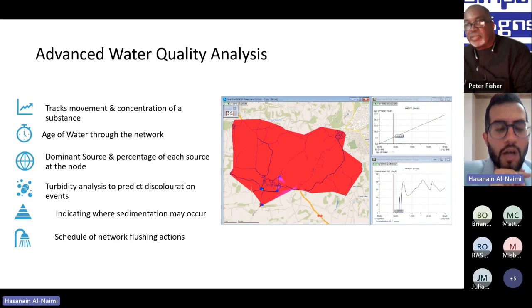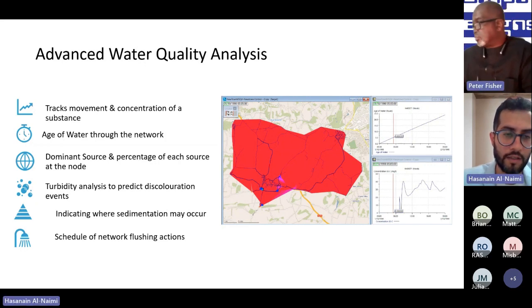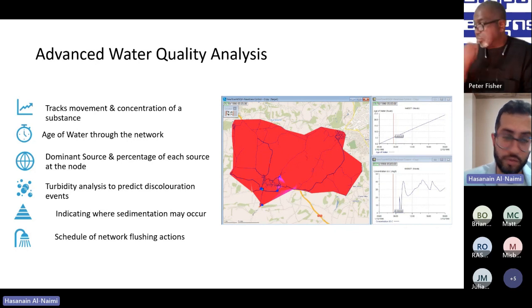How does the model handle that? You have to put in some data. If you have an age for the pipe itself, you can input that data. That means you have to assume a parameter for the roughness coefficient of the pipe. Yes, there is a roughness that you can change yourself, or you can take the standard roughness that is there in the code. You can take that, or you can choose it yourself. So it will take that into consideration in the calculation.